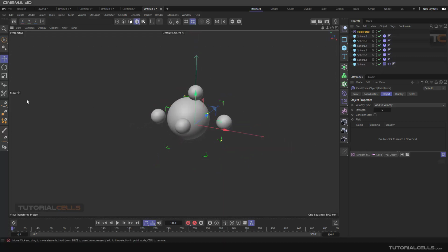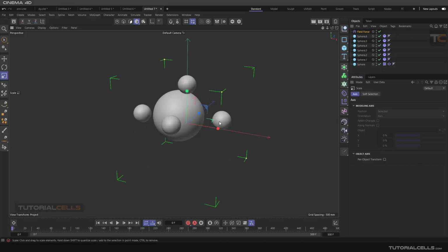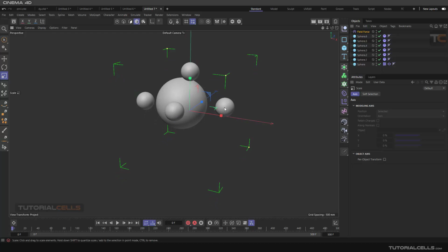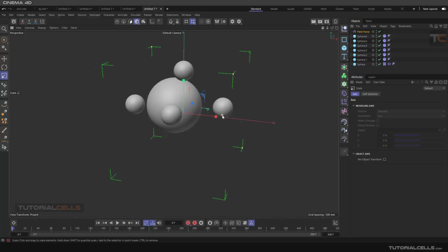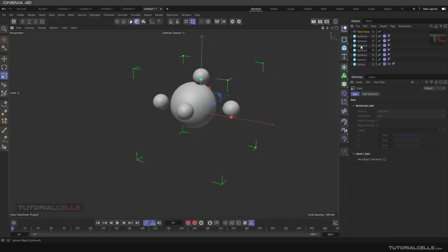The important part, as I said before, is the area of effect. If your scene is like this, make the affecting area of the field force bigger. Don't forget that, okay? Because we want to tell this radius, please snap to that sphere. The vectors you created here are ordering this sphere to snap to this sphere, so the area is very important. Going to the field force in the object, don't drop it in the field; put it in the object, this main sphere.